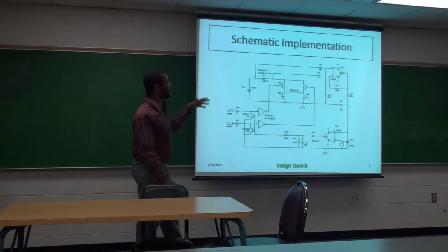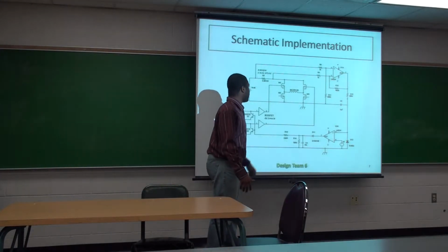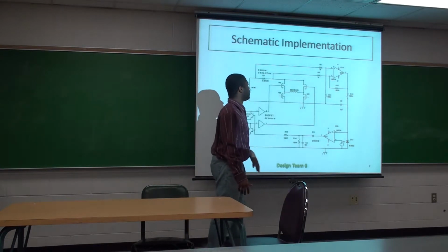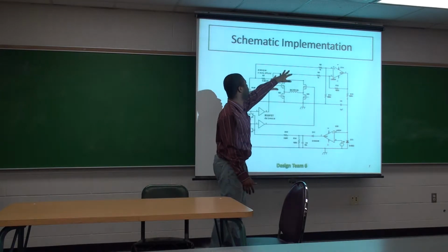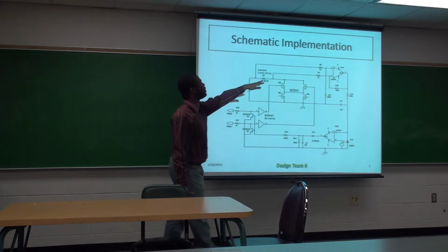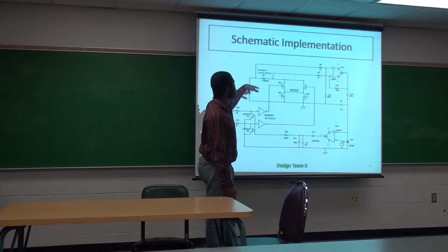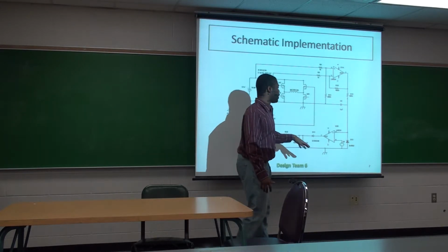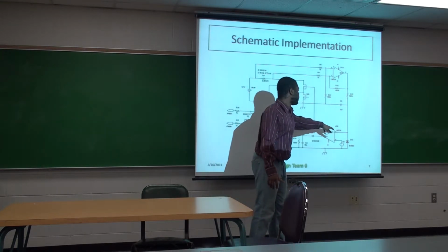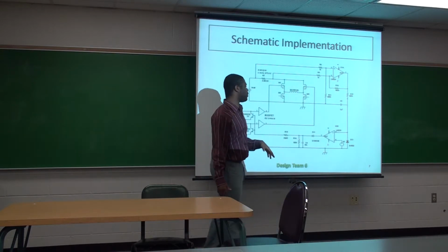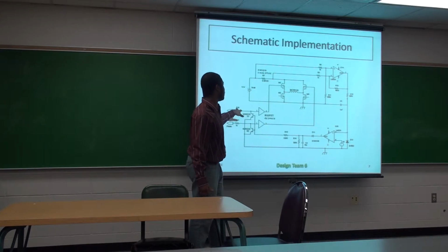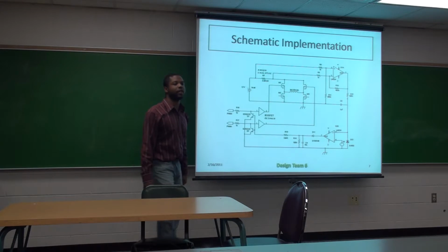This is an application of a speed controller based on our diagram that we had before. This is the H-bridge, it kind of looks familiar. And the new stuff is the overcurrent protection. The way it works is that this is a differential amplifier. So you sense the voltage drop across this resistor and feed it to a comparator where V5 is some reference voltage. If this output is greater than some threshold, you short these transistors to ground and basically shut off the PWM input to the H-bridge, protecting your circuit.